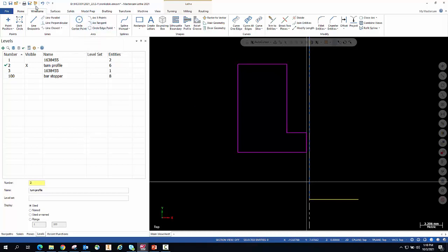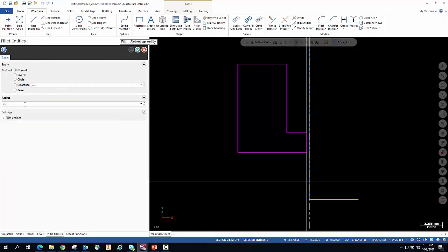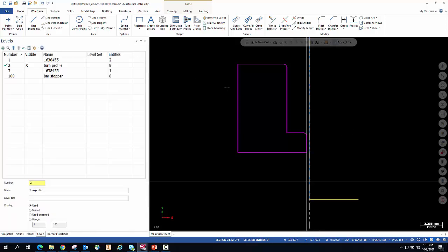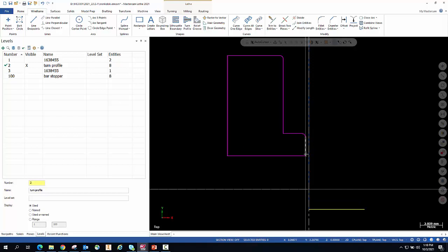We go to the wireframe and then we ask for corner rounding, fillet. So we are going to give a small radius, for example 0.3 mm. I like to have it over here. I like to have it over there. Confirm. And this is a hole at the center.